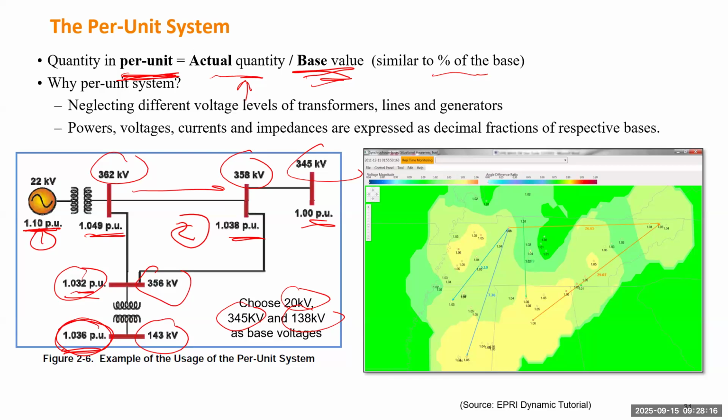At that time, such units were not very popular, but right now that has become basically the industry standard. You need to have such devices everywhere. But at that time we wanted to demonstrate the power of synchronizing all the measurements using a time signal, so you can see a really big picture of the entire Tennessee power network. You understand the network has many different voltages separated by transformers, but we use per unit values. So you see every number, those numbers just indicate the voltage in per unit. Most numbers are around 1.